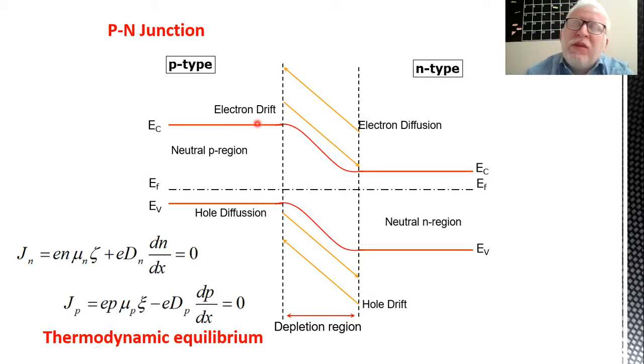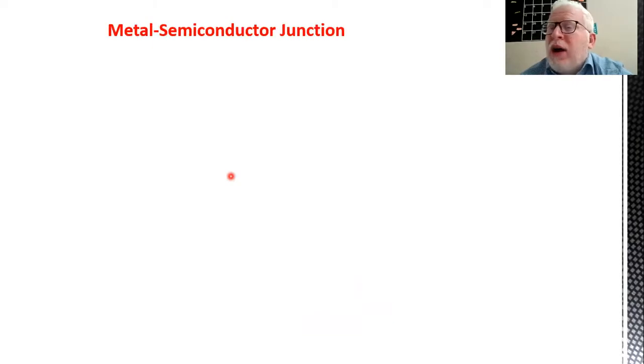Here, we have first to investigate how we can sketch the energy band diagram for a metal. Because usually in our materials, as well as in our semiconductor devices modules, we have dealt with a semiconductor energy band diagram consisting of a conduction band, valence band, Fermi level, and so on. But we have never dealt with a metal energy band diagram. So first, we have to introduce how we can plot the metal energy band diagram.